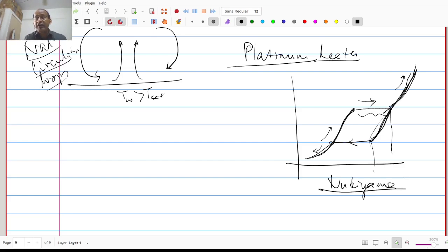when he tried to use the platinum heater and electrically heated the water, so he had, let us say, a tank of water, and he had a coil and he impressed the voltage across this, and this was a platinum coil. So he was able to measure the temperatures of the coil and the water around it. So he was able to get this part of the curve, which is the nucleate boiling curve, and this part of the curve, which is the film boiling curve, while heating. While cooling, he got all the way here, but then it jumped here and back here.